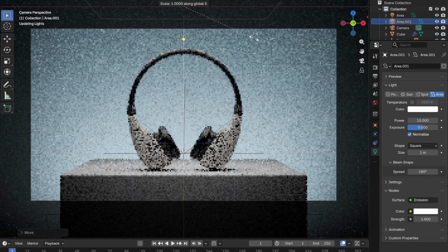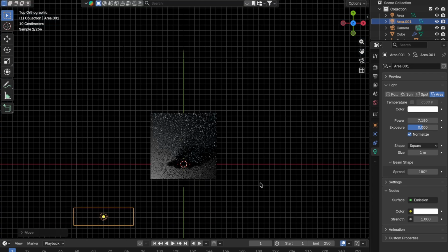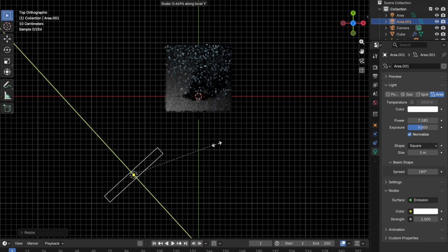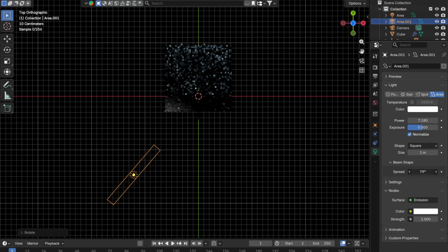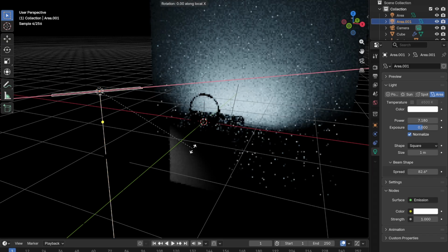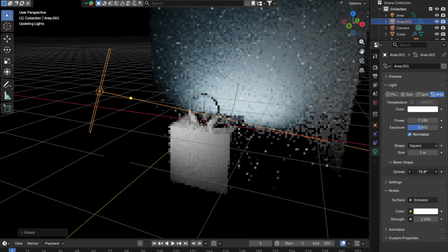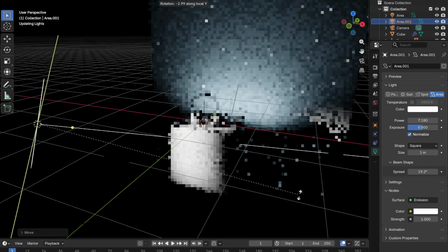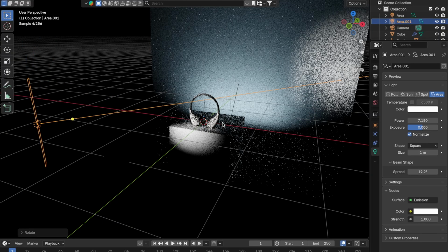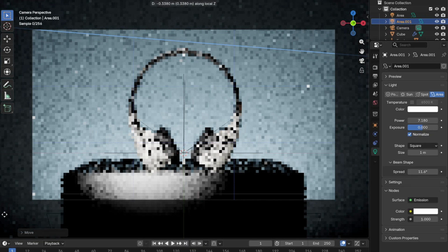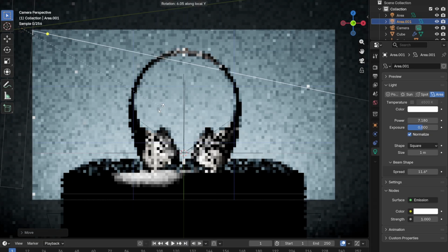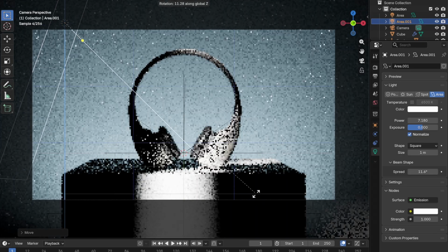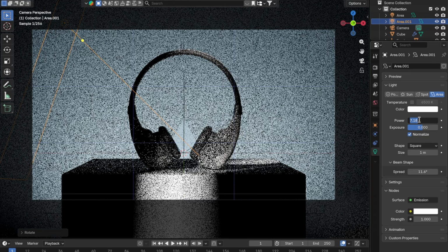And let's already start working on our headphones. For the first light I want to choose our orange narrow light, which will strike a specific point. For this we will reduce the spread to 80, 70, set it up to the point of interest, reduce the light maximally along the X, lower the spread even further to 11 degrees, and set up the light the way we like it to fall, right? So that it doesn't affect the cube, so that it strikes the specific point.